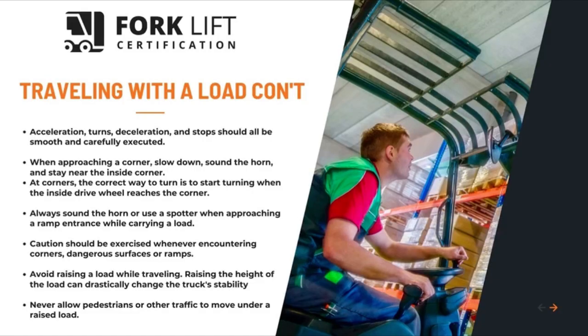Avoid raising a load while traveling. Raising the height of the load can drastically change the truck's stability. Never allow pedestrians or other traffic to move under a raised load.